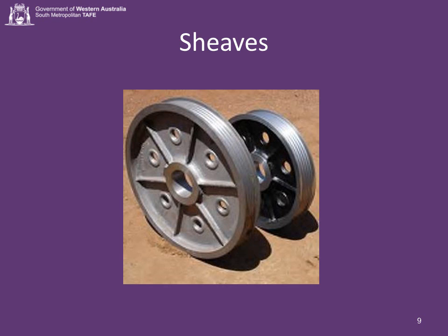In some cases, one drive shaft drives more than one driven shaft. When this occurs, more than one sheave can be mounted on one shaft. This is necessary only when sheaves of more than one size are needed. If the drive sheaves are the same size, one multi-belt sheave can be used. Most sheaves are balanced and capable of belt speeds of 110 km per hour, or roughly 2,000 meters per minute.